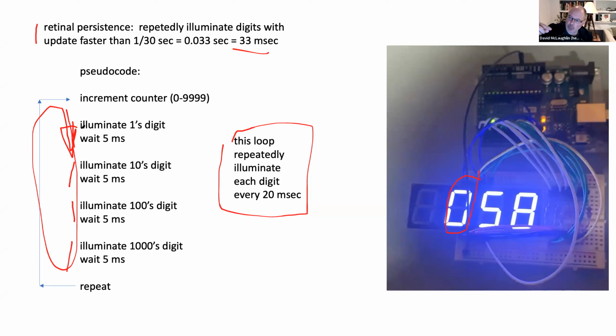So I have that. This is important because when you're building one of these things, there's a lot of wiring going on, and the first time you try to make it, the LEDs aren't looking right. So by also writing the information out to the serial monitor, you can see what's showing up on the screen. You don't have complicated hardware there. And so the only difference here is I pulled in my UART codes. These are the UART functions that we're always talking about, okay?